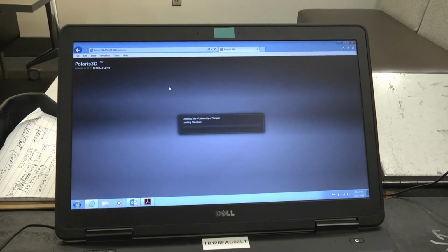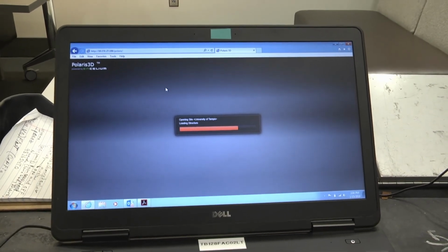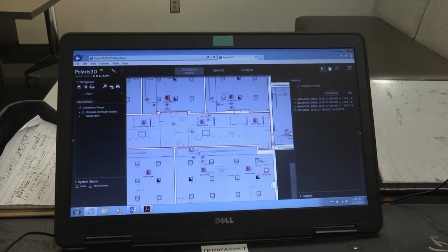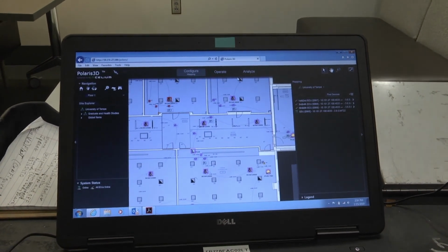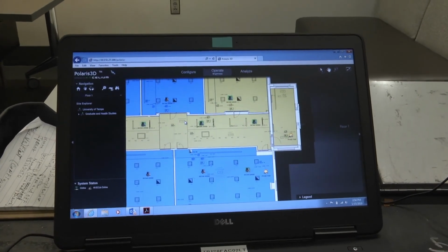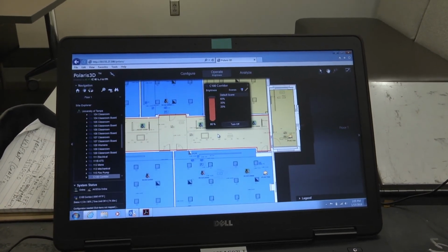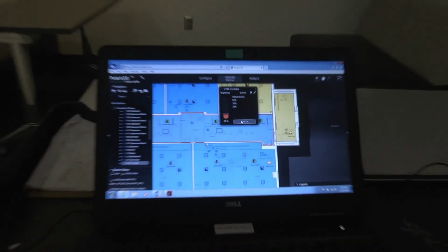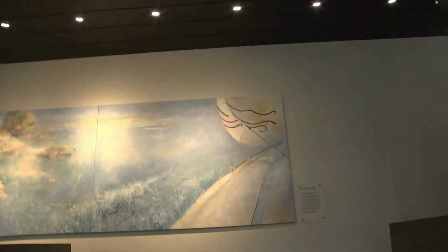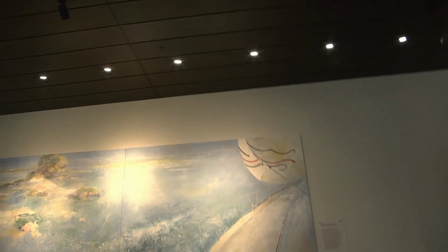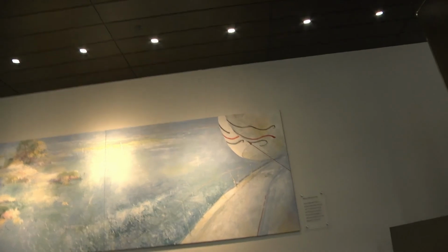So once this comes up, we're going to test the zone. Right, we're going to turn the lights off in the area and see if those devices react. So we're going to operate mode, the top, brightness. All right, now we're going to click on the zone, anywhere on the zone, and hit turn off. Right? Now, you notice it didn't go completely off because there's an off state brightness set at 20%, but we can override it and check it out per se, right? So turn that back on.